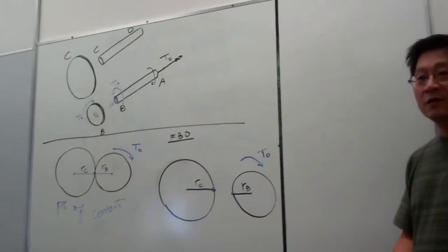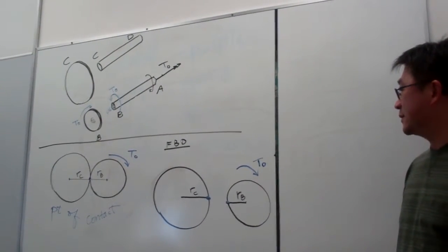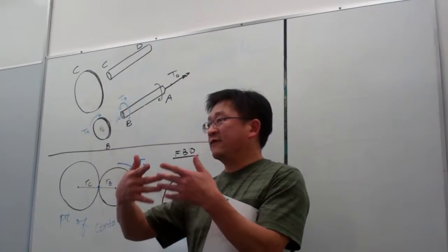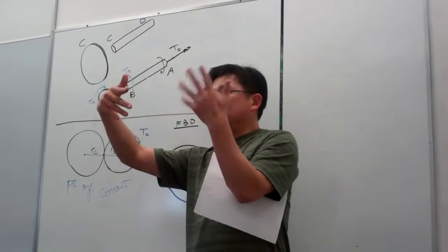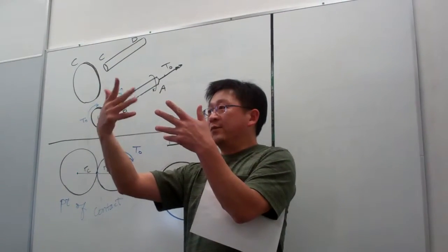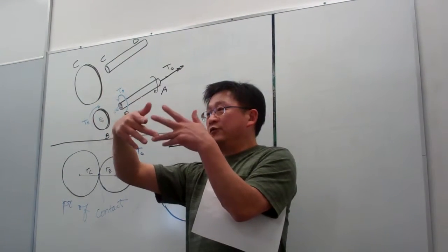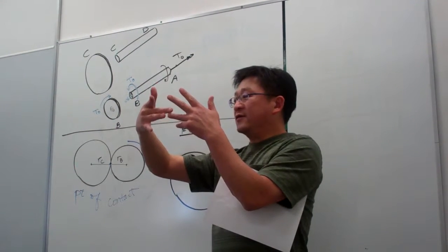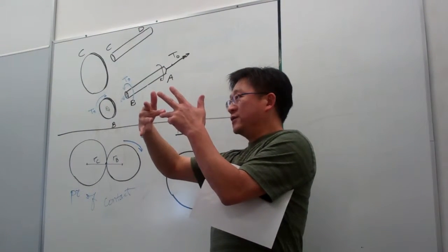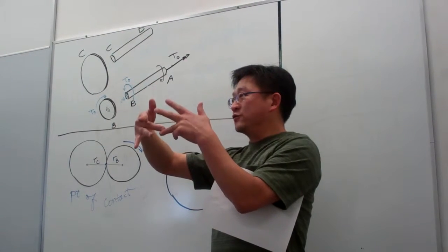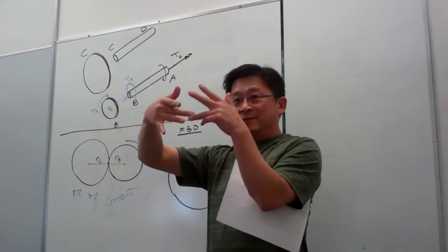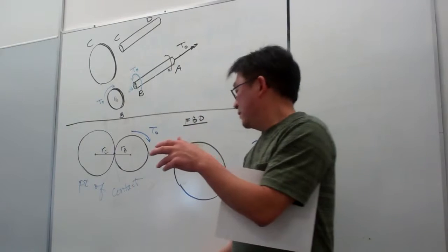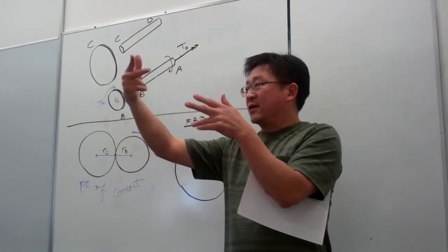Okay, and now we are ready to explain the transmission of the torque. Again, from the beginning, I mentioned the two sets of gear, this is a driving, this is a driven. So driving is to apply the torque and to rotate through a pair of engaged teeth. So here you can see, once I drive here, can you feel on the two teeth, this one applies the force to press this down. Can you see it? So that means at the contact point, this one is the driving, I press down basically on this tooth.